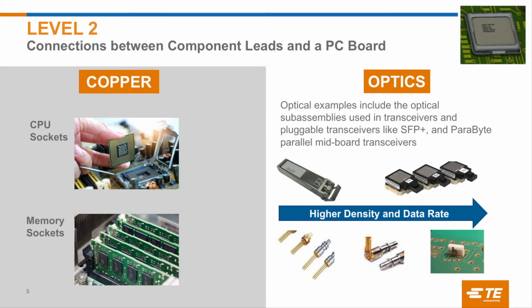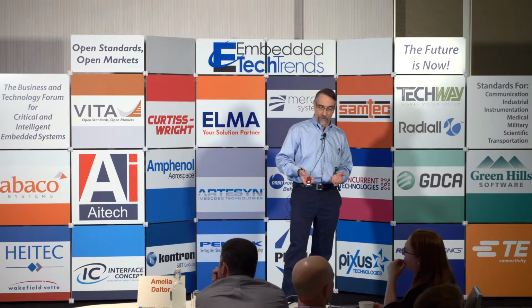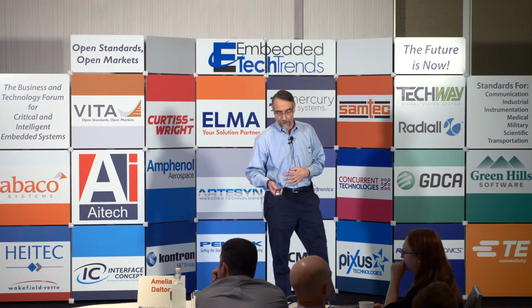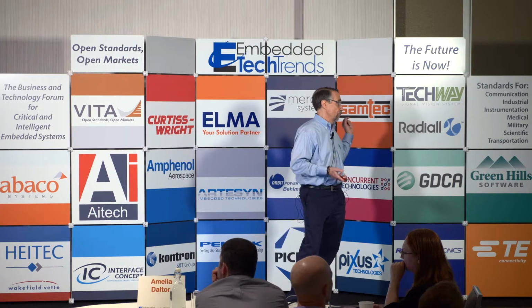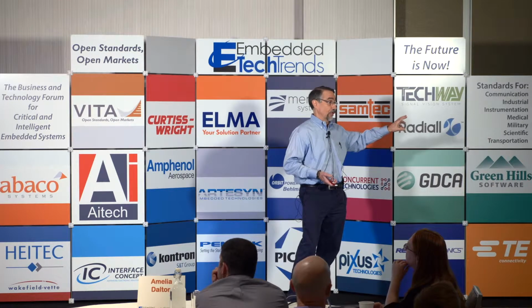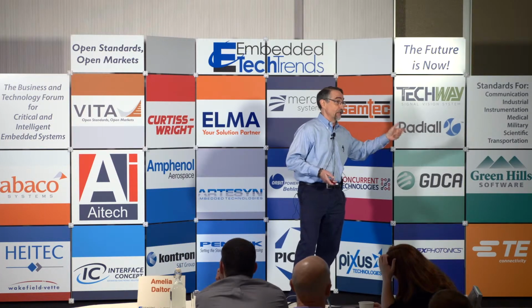In the electrical world, that may be the traditional solder of the lead frame to the board, or a socketed device, or a CPU or a memory socket. In the optics world, now you're into pluggable transceivers, or the subassemblies inside those transceivers. They can be discrete, single channel 10 gig devices, or they can be the array devices that power the parallel transceivers that several of the folks here have already spoken to. But the trend you see there is that two things have continued to happen. The speed's going up, and the density of the optical connection at the transceivers is rapidly moving away from discrete single channel devices to array-based devices.